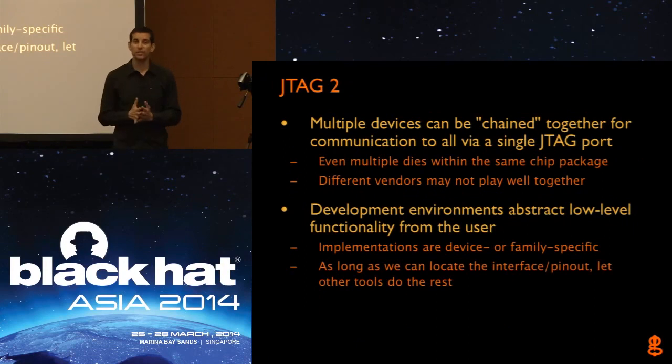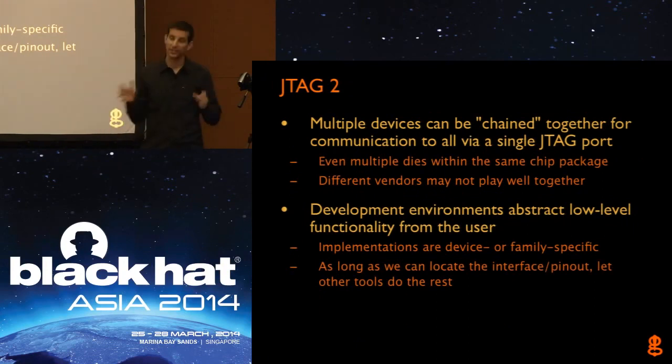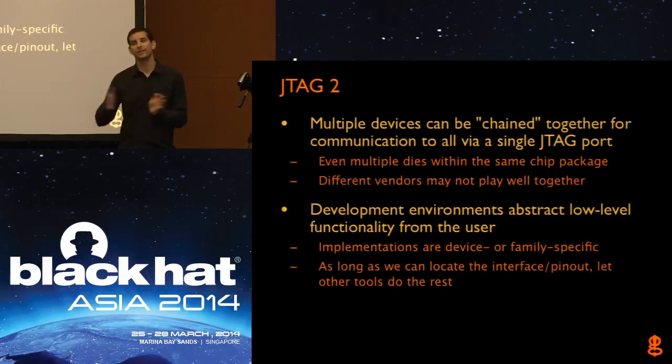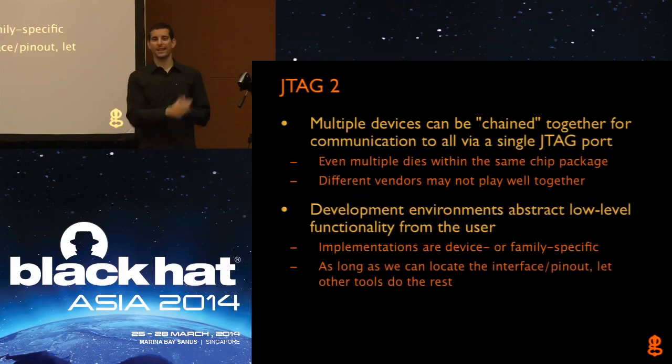What's also interesting about JTAG versus a lot of the industry standard vendor-specific interfaces is you can have multiple devices connected to a single chain. So now you can have one JTAG connection on the board that connects to, say, 3 or 4 different devices on a board, maybe a CPU, a baseband for a mobile phone or something. Or it could be multiple chips within a single device.